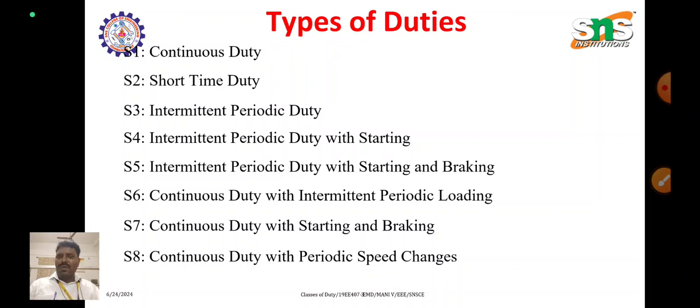There are 8 types of duties from S1 to S8. S1 is continuous duty, S2 is short time duty, and S3 is intermittent periodic duty.